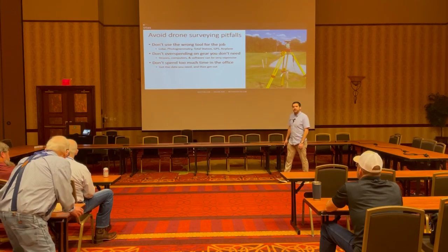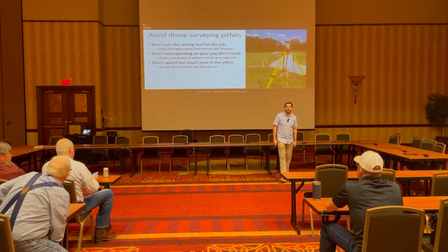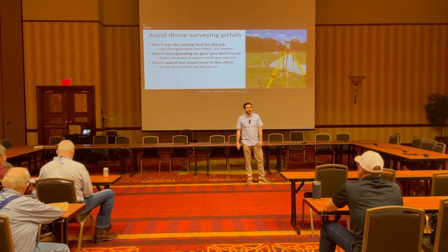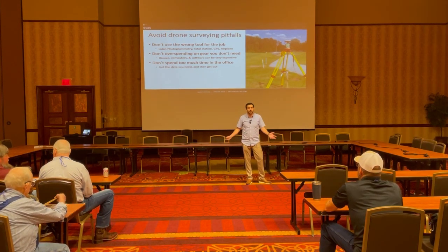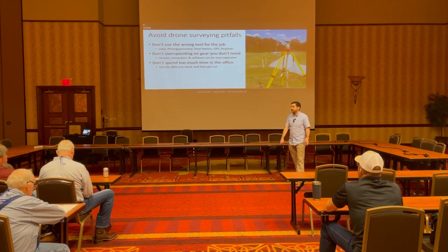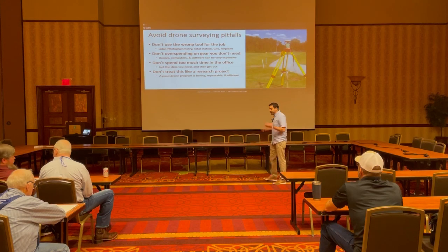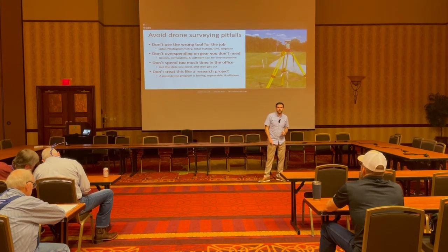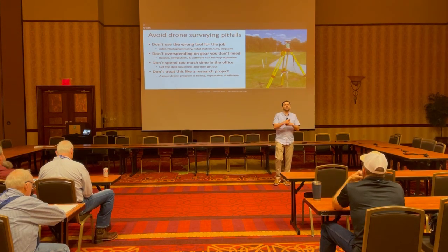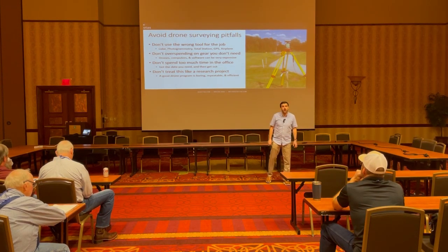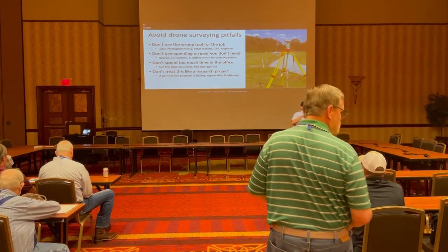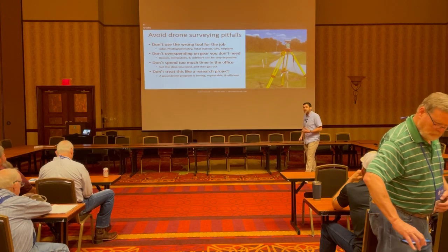Also, don't spend too much time in the office. Another very common pitfall. People say, wow, look how quickly I was able to fly this site. Now here's 250 gigabytes of raw LiDAR data. Let's figure out what we can do with it. And it takes 80 man-hours of processing, and you're toast. And again, don't treat this like a research project. A drone program should not be a research project. You're not trying to figure out what you can do with drones. You're trying to get your survey done in the most accurate, highest quality, and most efficient way possible.